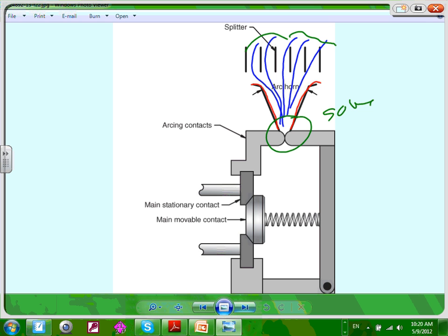So you control them. In the vacuum, guys, this is your cylinder that you're going to interrupt. So look at the stationary contact. These are my arcing contacts, the ones that are going to be arcing. The contacts that you want to save mostly are the right contacts. I don't know if you guys can see these. These are the contacts that close and open. This is the stationary, and this one is the moving one.